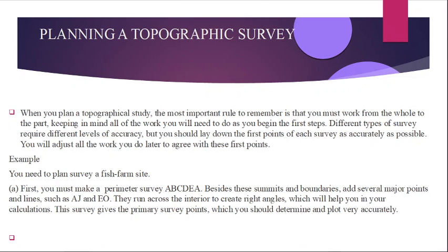Planning a topographic survey. When you plan a topographical survey, the most important rule is to remember that you must work from whole to the part, keeping in mind all of the work you will need to do as you begin the first steps. Now, what is the meaning of whole to the part? Whole to the part means to divide the area to be surveyed, or the region to be surveyed, by help of a number of triangles or number of blocks.